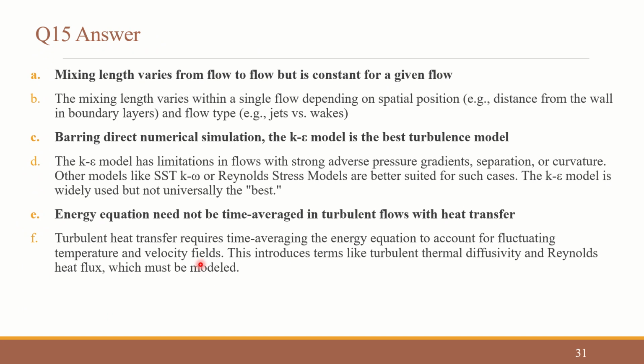So turbulent thermal diffusivity and Reynolds heat flux are additional terms which will be introduced and we need to model those. So time averaging of turbulent flows with heat transfer is required. We cannot neglect the time averaging in those cases. The energy equation needs to be time averaged in turbulent flows with heat transfer. So the statement is also false.